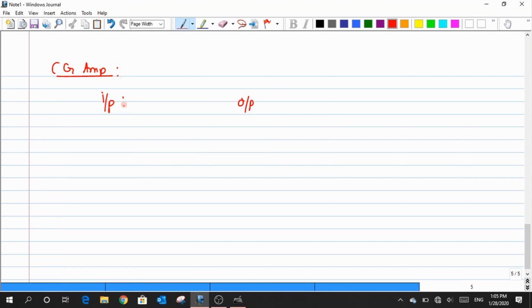It's actually symmetric, sir. It is actually symmetric, but there is one particular problem that I gave during the activity. Do you all remember that? Only very few people had addressed it. The second part of your last problem had a circuit which is almost like common gate, but we had interchanged this. We had fed the input to the drain and taken the output from the source. Normally for a common gate, we feed the input to the source and take the output from the drain.